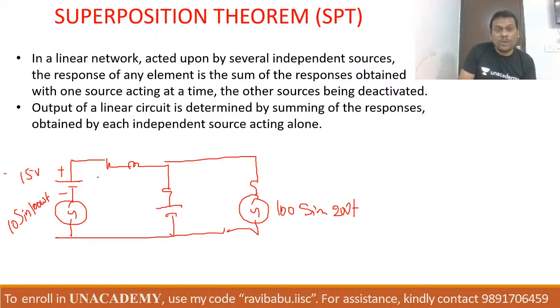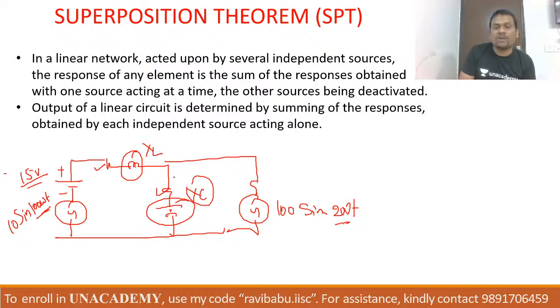We are not worried about the resistance mainly. We are worried about the inductance and capacitance. When we operate our system by a DC supply, in steady state the inductor and capacitor will be short or open, depending upon the type of circuit configuration. Due to omega and 2 omega, the reactance of L and the reactance of C will vary. So XL and XC will depend upon omega. If omega varies, XL and XC will vary and the performance of the system will change.